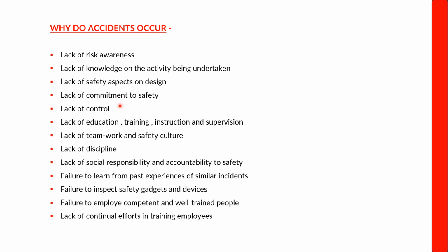Before using any hand tools, you have to do a visual inspection. For example, if any lifting is being undertaken, the standard says that the rigger is responsible for inspecting the lifting gears before use.